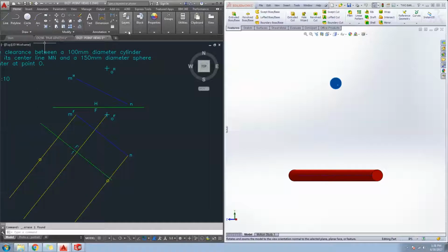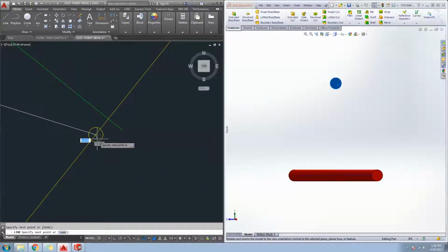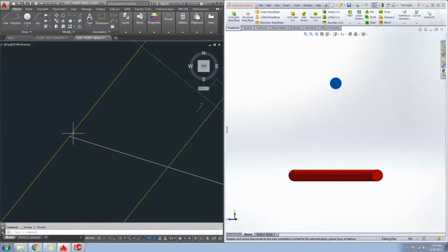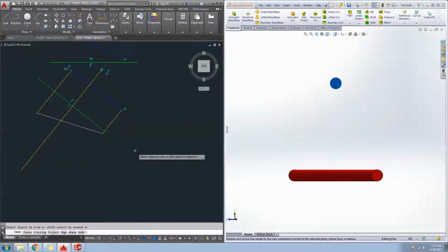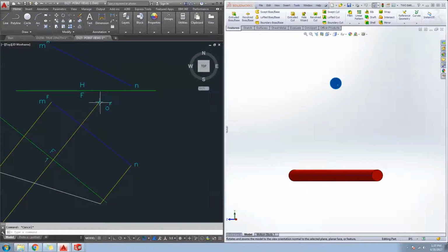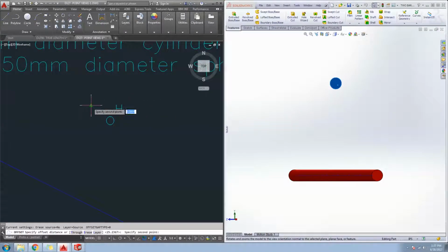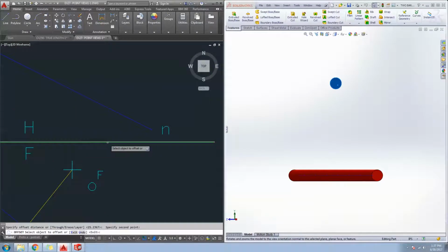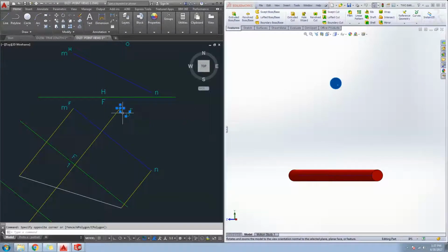We'll delete the folding line, move to the object layer. Connect those 2 guys there, and perfect. We will trim these away, and that'll be the line MN. This guy right here, point O, we'll repeat the same offset that we've been doing from point O to folding line, offset, and then we'll go ahead and just copy that guy.